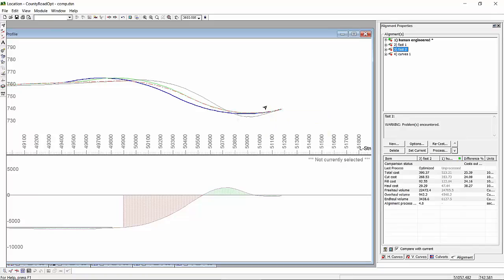Let's see what's happening in terms of the cost. In the original test we made, the cost was about 468,000, and the reduction was, remember, 10%. Here we get down to 390, and the reduction now is 25%, right? That is expected as we lower design speed, but we were not exactly sure how much of an impact this change could make. Now we have been able to quantify that.